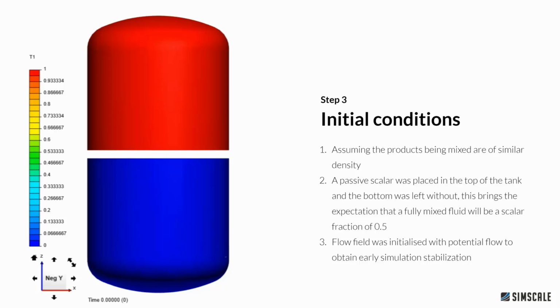That's incredibly handy, and that's also available on most of our standard CFD solvers. So if you are setting up a transient simulation, I would recommend using that to give you some good initial conditions. What that does mean, however, is that you are starting with some sort of fluid flow field, so you haven't got an entirely stagnant flow to begin with. If you are interested in looking at a flow field from absolutely stagnant, then you would not use this parameter. But it wouldn't affect your results that dramatically if you were to use it. It depends what you're interested in.